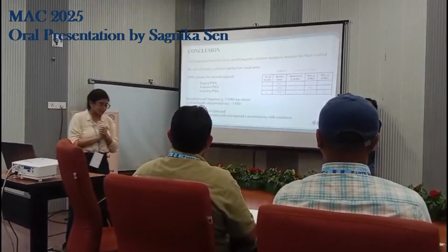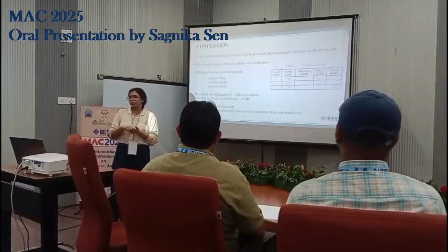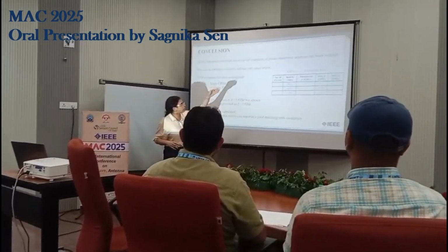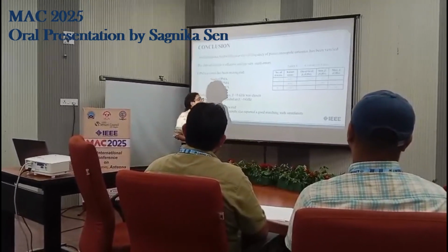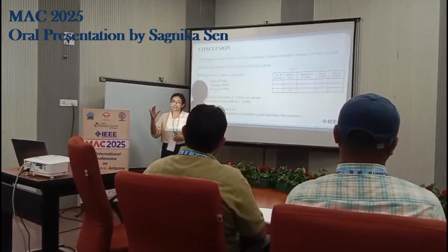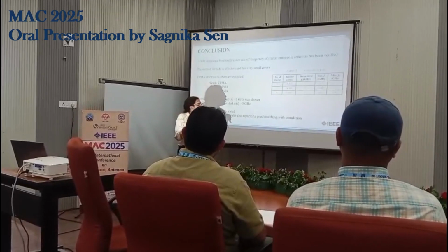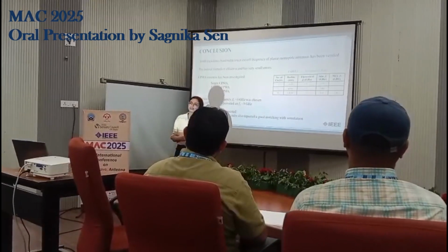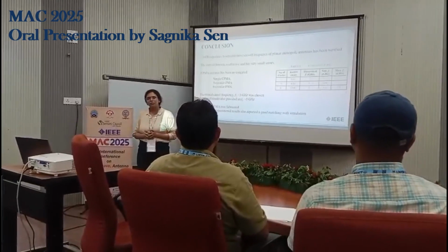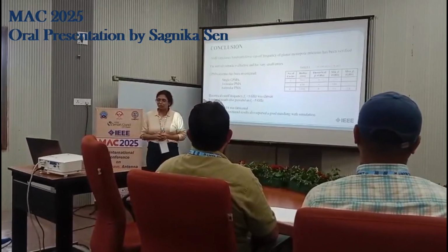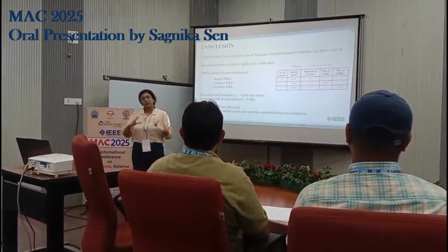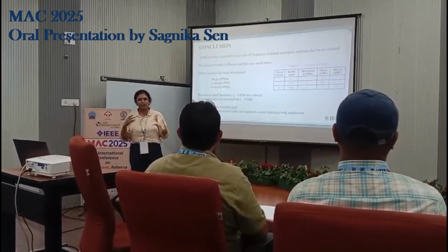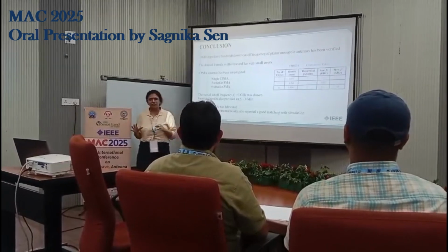Now, coming to the conclusion, if you can see the table here, as I increase the number of circles, the simulated FL value also increased, suggesting that there is an error factor being introduced. My inference is that for basic planar monopole antenna designs, the FL formula holds valid. But when you increase the complexity, the antenna engineer must be wary before using it because some sort of error will be introduced.